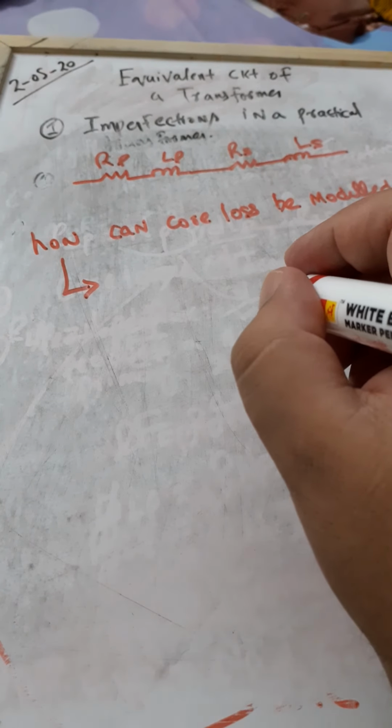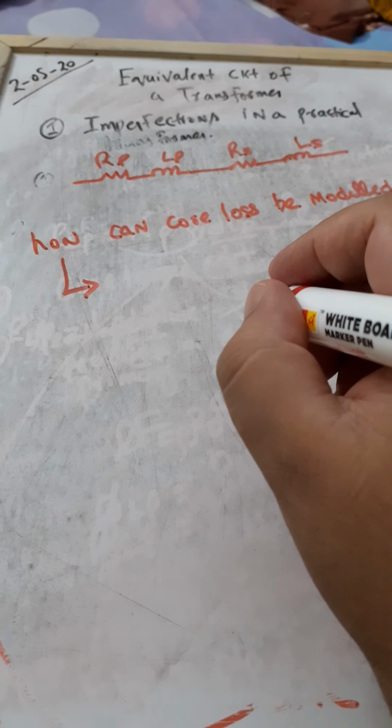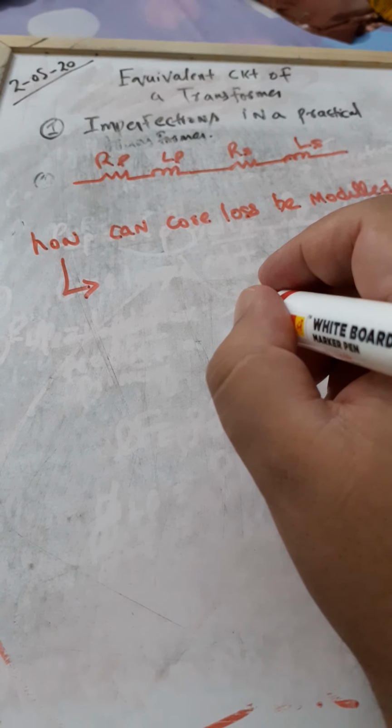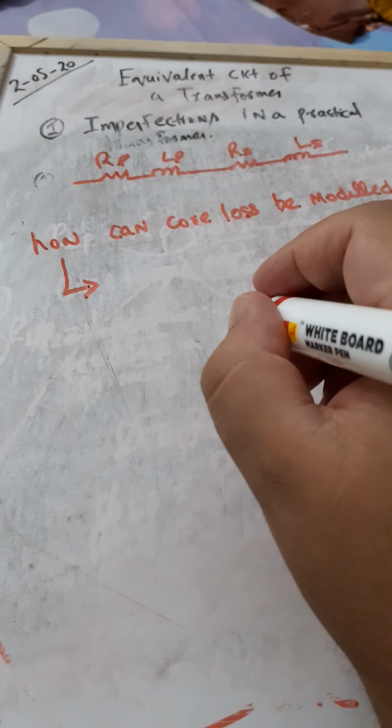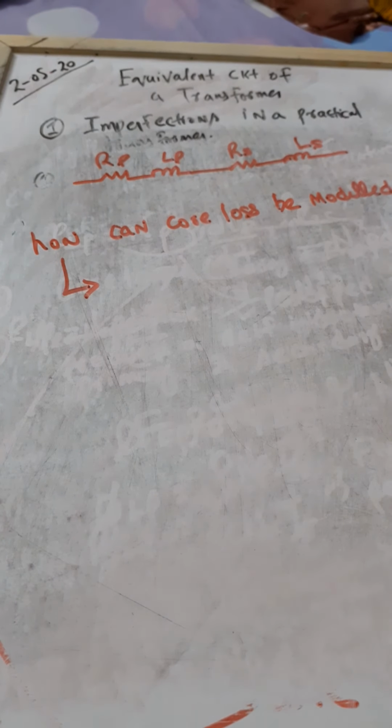See, what happens is that when you are giving the supply to the core, there is an excitation current, and that excitation current excites the transformer. Whenever in big stations you are rigging up or installing a transformer for the first time, some of you might have relatives working in the electrical power development department, or have knowledge of this field. There is some charging of a transformer that takes place initially. So this basically is to establish that magnetizing current.